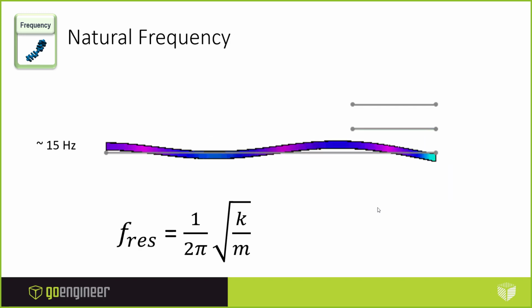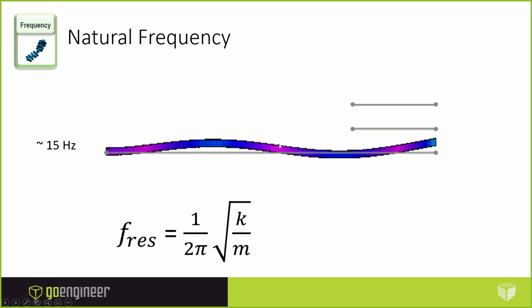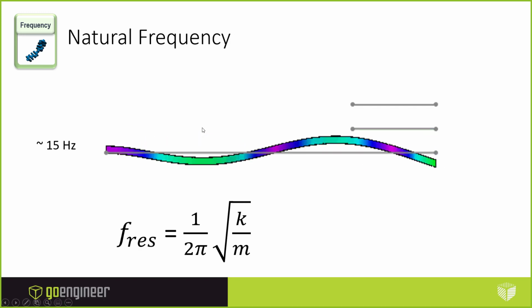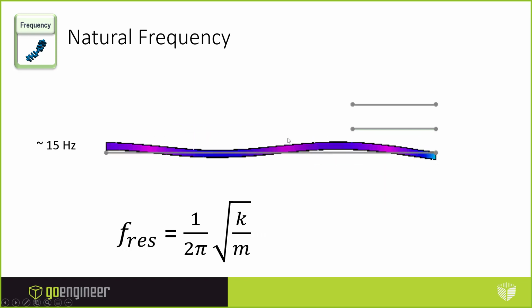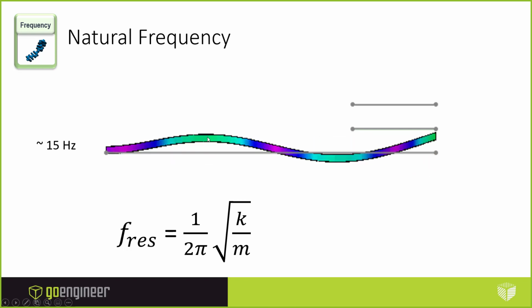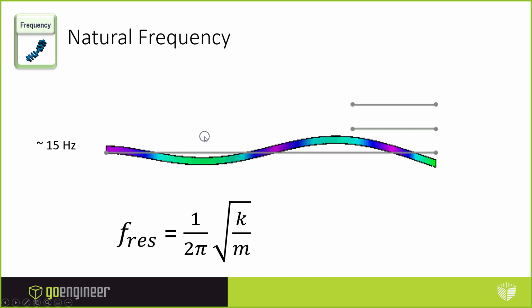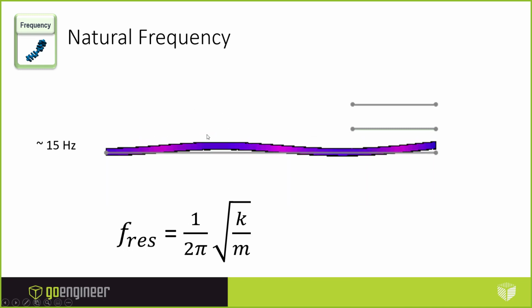Let me go actually back to one of these. I can use those to make better design decisions, such as where I may want to place supports. If this was a circuit board, resonating, I may want to place a support right about here. It'd create a different resonant frequency here.